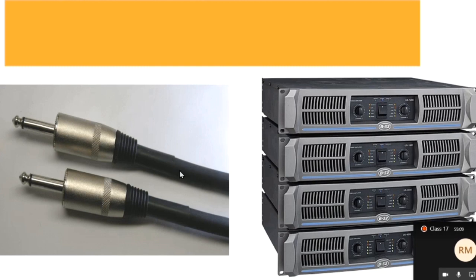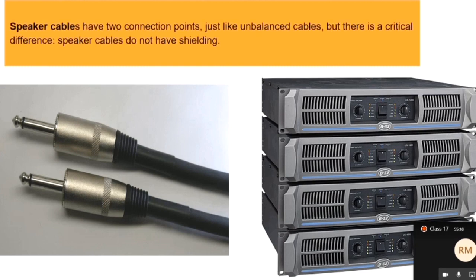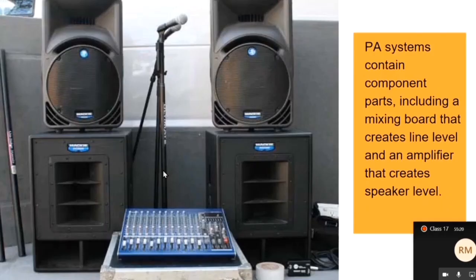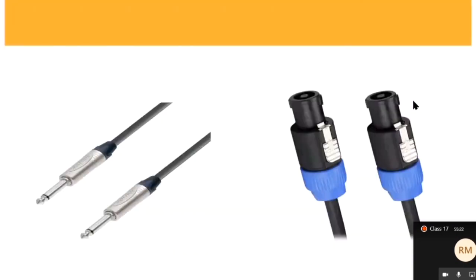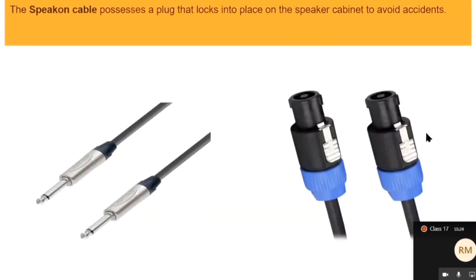Now, happily, the technology of speaker cables has pretty much abandoned the phono plug. And what you will encounter is Speakon, I think that's a brand name. So yes, these are both speaker cables, but this variety here locks into place, which means that you plug this into your speaker cabinet and you twist to the left or to the right, and then it just can't come out.